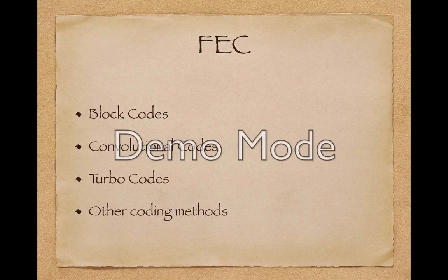On the contrary, convolutional codes are typically decoded using soft decision algorithms like the Viterbi, MAP, and the BCJR algorithm, which process analog signals, which allows for much higher error correction performance than hard decision decoding.